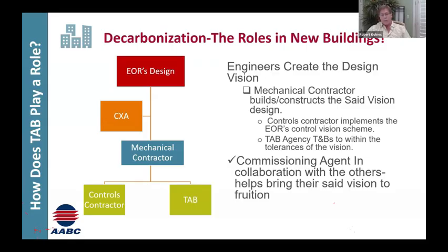When I got to cross-referencing the submittal data, I saw that the control submittal, their package and selection of the pressure independent control valves, tallied up to the same GPM, but the order was put in for the control valve bodies to be 3-way type configuration. Well, that's not going to work in a variable primary system. So I looked further into the drawings, and in the detail sheet for the chilled water coil, the piping configuration was identified with the 3-way control valve. And it didn't say anything else about a 2-way or only having them in certain locations.